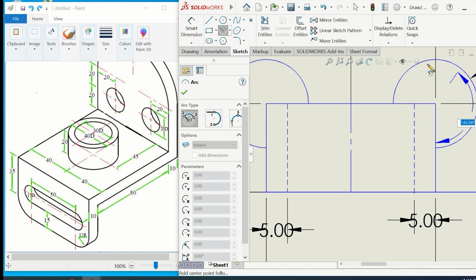It's drawing the opposite arc. I rotate my mouse. Did you see how? To show SolidWorks that I want to start from the other side, I rotate. It's not taking it this time. Yeah, it is. Okay, it did. Let me rotate. Okay. So here, guys, you just rotate, and then SolidWorks would start drawing it from that. If it doesn't, we can always repeat again.